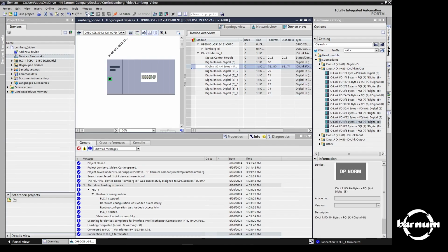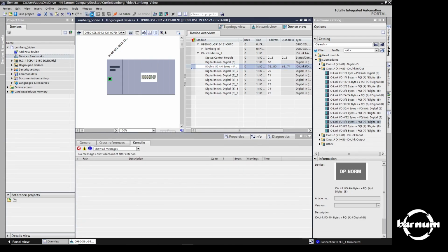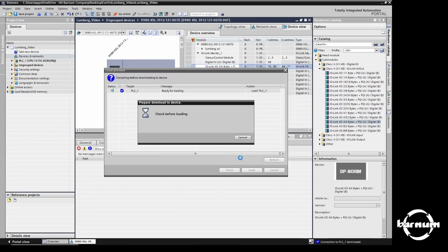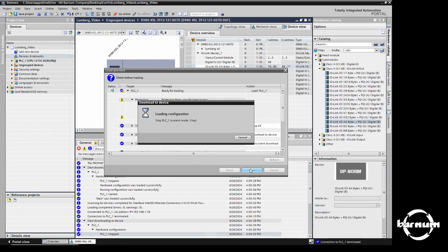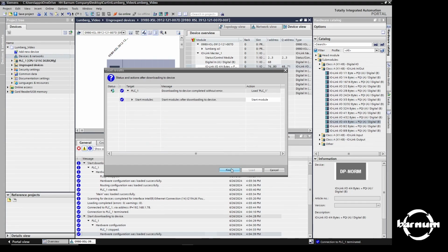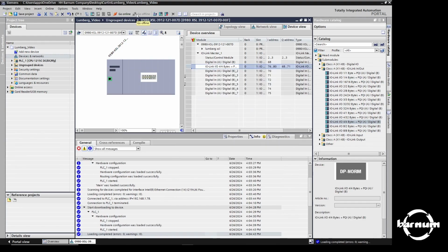Under Submodules in I/O device, you can find all the options to configure each port. Click the desired option, drag it onto the free IO-Link spot we just made from deleting, and be aware of the data size options when selecting your IO-Link, and make sure you have enough that closely matches your IO-Link device. If you're unsure, err on the high side instead of the low side.